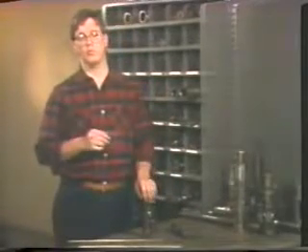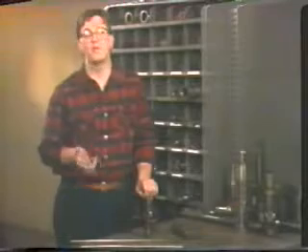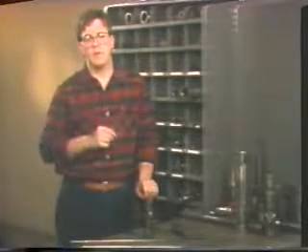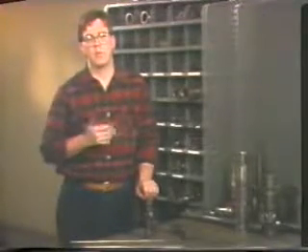Sometimes, in spite of our best efforts, the wireline breaks or tools become stuck in the wellbore. Often both wireline and tools are lost in the well and must be fished out. Let's identify now the common fishing tools and give a general explanation of their purpose. The wire finder is used by the specialist to locate and coil the upper end of the wire line so that it may be retrieved with a wire grab.